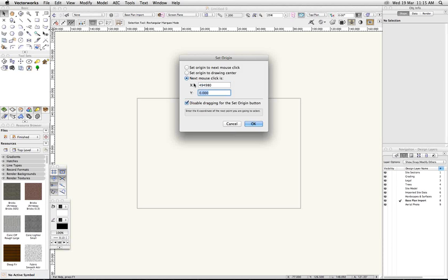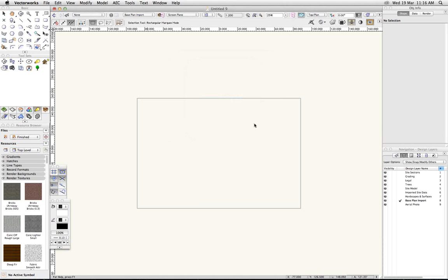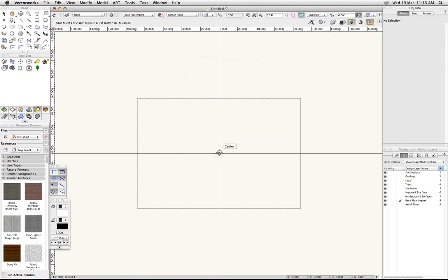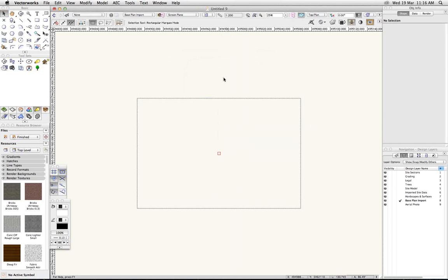That's my X. That's my Y. And then I'll just choose to put those at the center, and you can see the ruler shift. So now again, I'm in good shape. I'm taking care of that shift I did with the center after import. And I use this shift of origin as a constant in the project. I do it in every file.